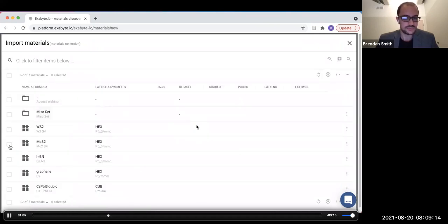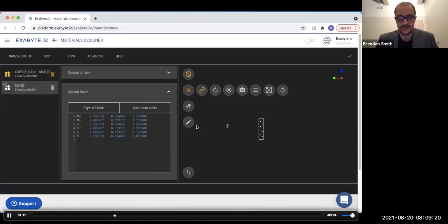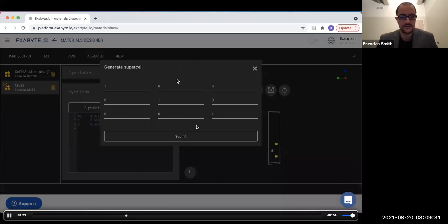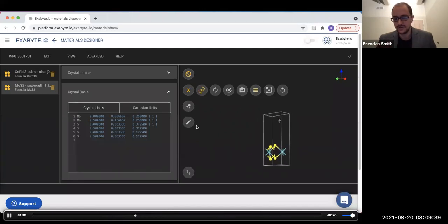Okay, click the molybdenum sulfide and then select items. So now that we've imported it, we're going to do like we did in the last 3 examples, where we're going to make the molybdenum sulfide monolayer. And now we're going to apply a transformation matrix to switch the lattice system. So this is just a simple transformation here. And you can see now we're in this rectangular orthorhombic frame.